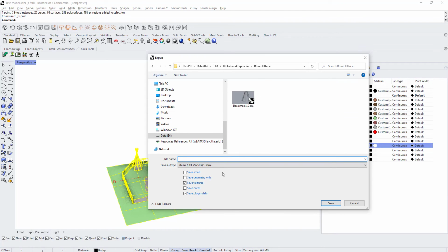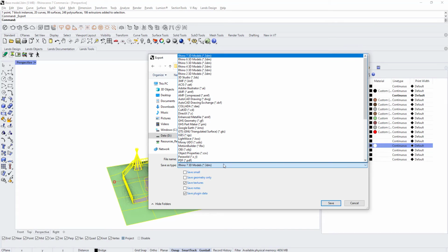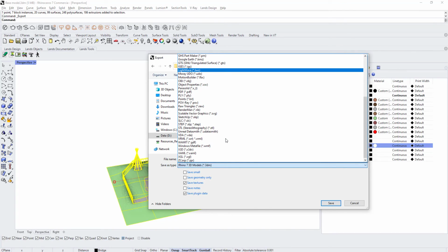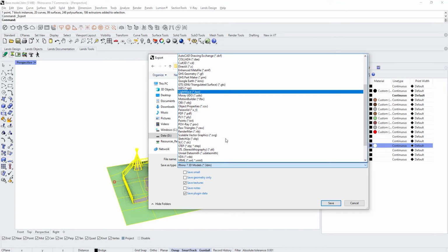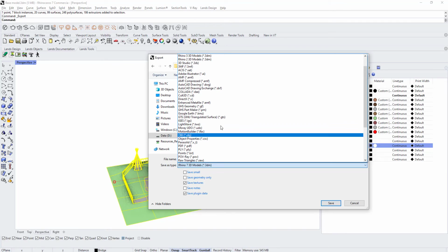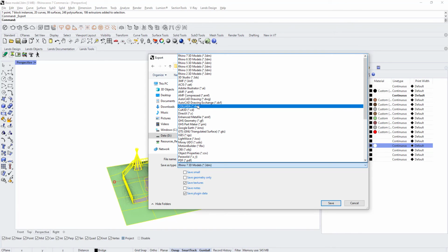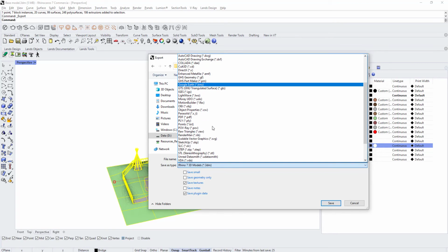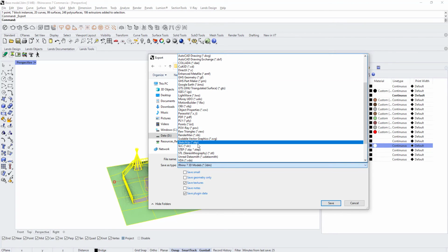So one thing to be kept in mind is that we could use various types of files for importing in Lumion. My usual go-to would be the Collada file, which is right there. It's a .dae format. It's the very basic kind of native file format for Collada, but you could also use the SketchUp format, and it's right there.